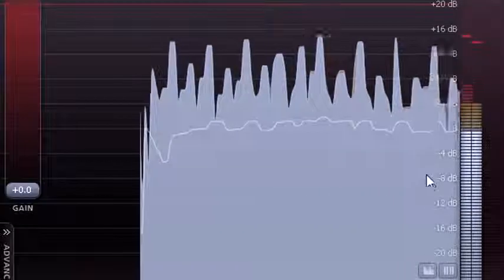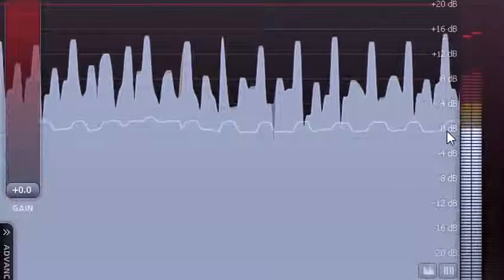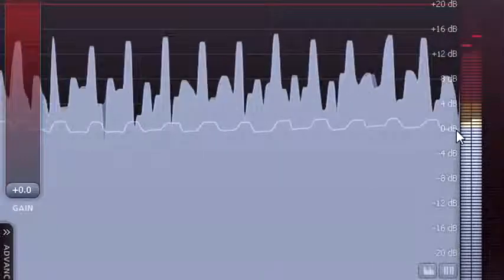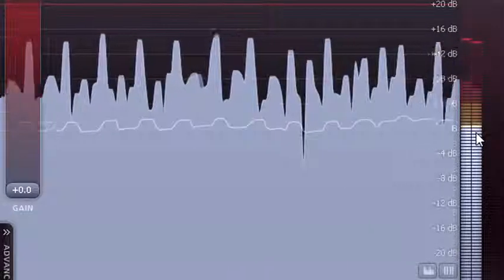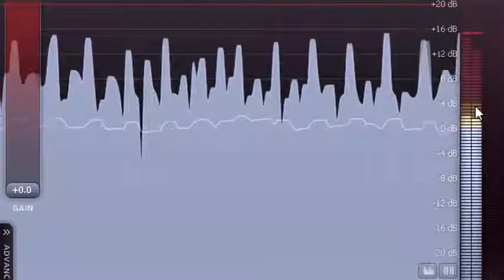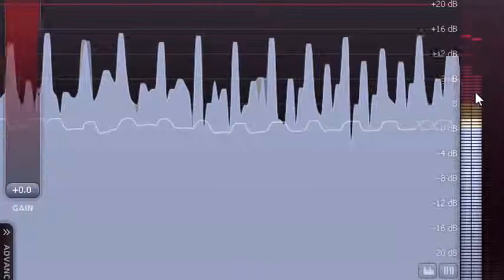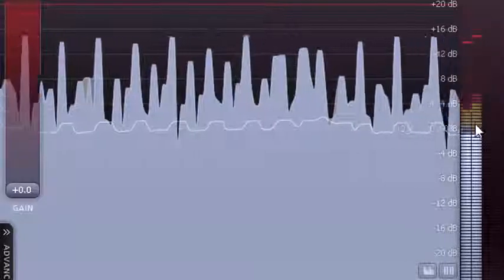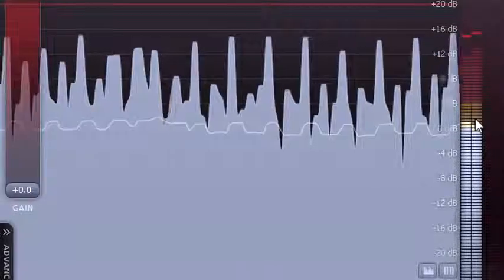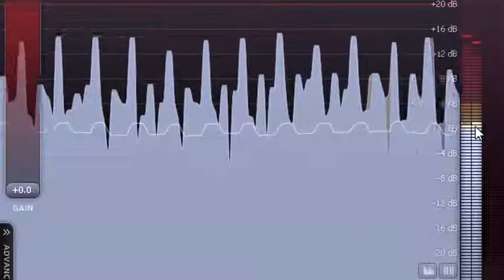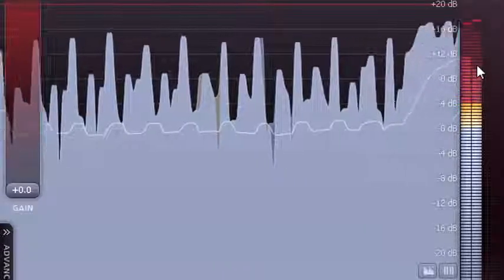And the first thing to notice is that, unlike most digital meters, 0 is no longer at the top of the scale. Instead, we have a nominal unity gain at -20 dBFS, with a 4 dB yellow zone above it, and a red zone above that. RMS levels should be kept within the yellow region for loud passages, and should only enter the red zone for occasional very loud fortissimo sections.